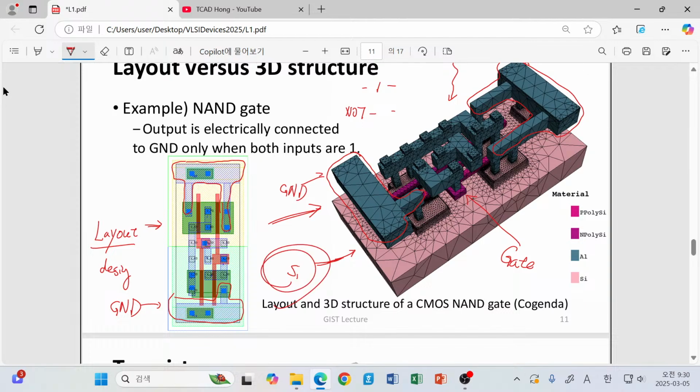So silicon underneath this gate part is working as a switching part, the channel region. So by changing the electrical conductivity at that point, we can connect one node to the other, or we can make the disconnection between them.